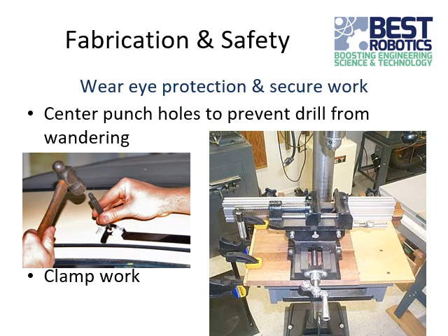If you're using the drill press, you need to make sure it's clamped down to the drill press table. A lot of times there'll be a vise or something attached already that you can use, but if not, you can clamp it down with normal clamps.